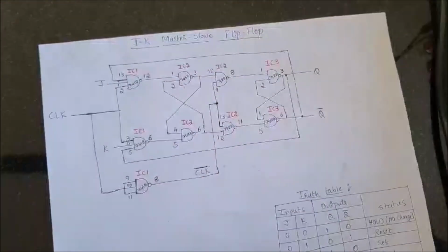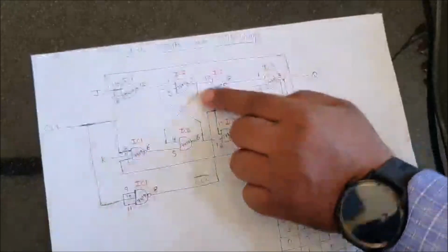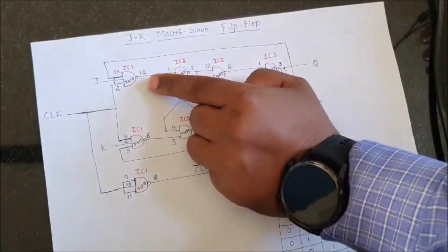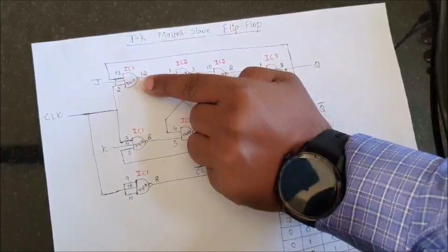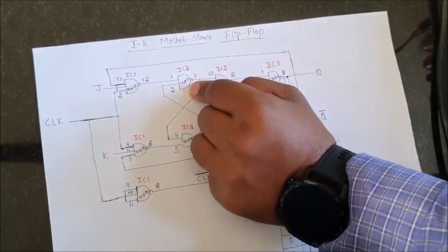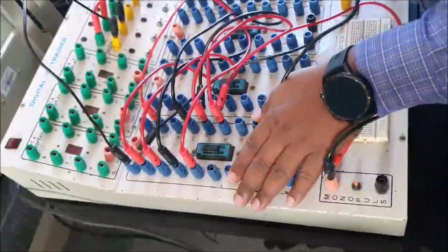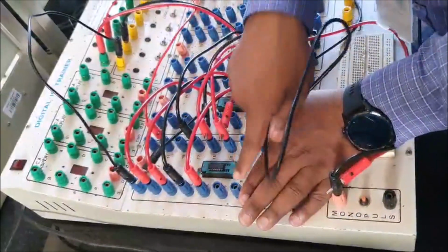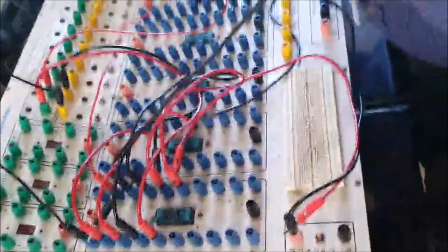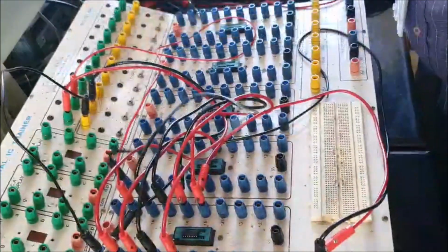Now moving on to the second IC, where the second IC has four 2 input NAND gates. I will take up the first 2 input NAND gate. Here the first input is from the 7410, that is IC1 12th pin, connected to the first pin of 7400. See here, this is 7410. Here one end of the patch cord is connected to the 12th pin. So this is 7th, 8th, 9th, 10th, 11th, 12th pin. Another end is connected to the first pin of 7400, that is IC2.